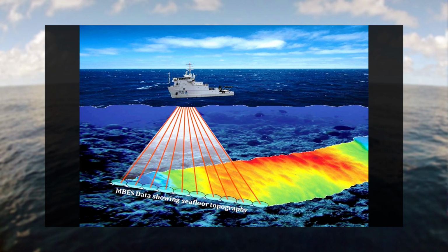The critical technological evolution lies in the transition from single beam to multibeam systems. Rather than a single downward-looking beam, an MBES transmits a fan-shaped array of hundreds of narrow adjacent acoustic beams across a wide swath perpendicular to the vessel track. This methodology yields a dramatic increase in data density and spatial accuracy.